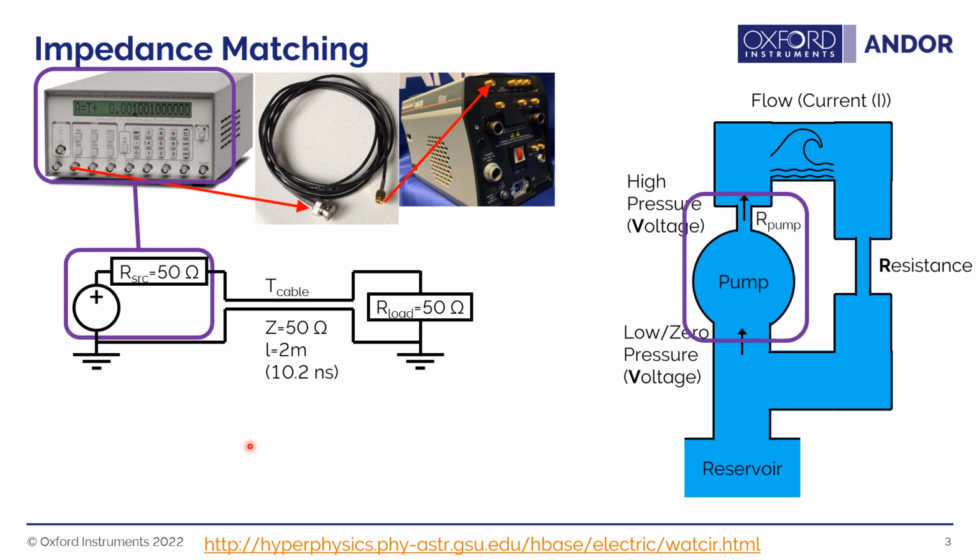So first of all, the first component of each of these is the pump of the system. The thing that's creating the pulse, in the electrical circuit, it's the voltage pulse, the TTL pulse that's traveling through the circuit. So this is the digital delay generator here, and sometimes this has a resistance to the pulse built into the delay generator, and sometimes you pick it within the settings, or you can externally add a resistor in series when required. So you would need to read the manual for each delay generator to know what it needs.